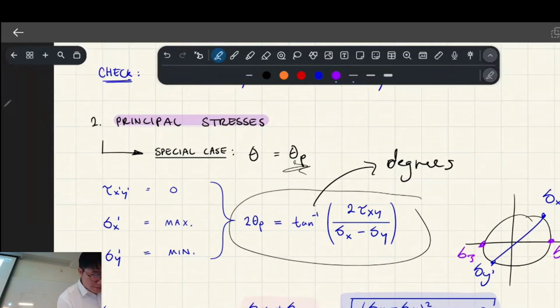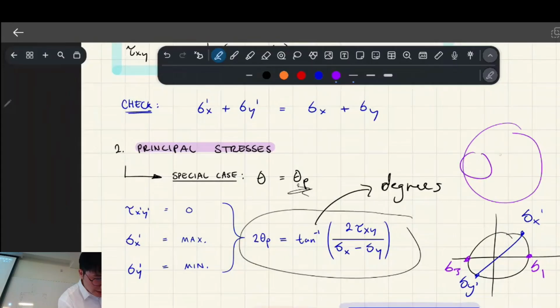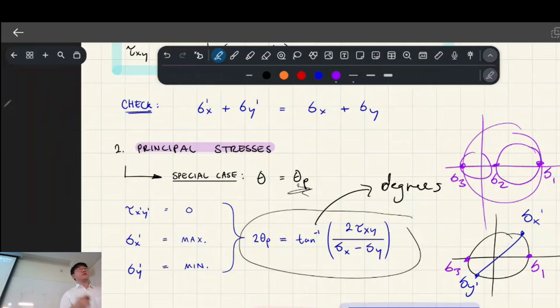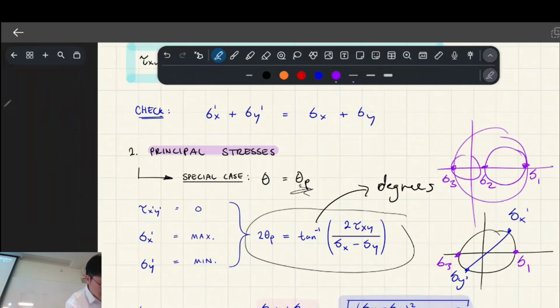The 3 comes from the other version of the Mohr circle, which has the triaxial plotting. The notation is that this is 3, this middle one's 2, and this biggest one's 1. But how the formulas translate over is sometimes people call the smaller one 2, and sometimes call it 3, once it's translated to a Mohr circle that only has one circle.